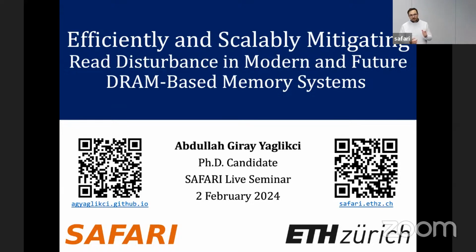That is also something critical for patchability. For example, there is a mechanism called Graphene that comes up with a very good detection mechanism based on the Misra-Gries algorithm, a frequent element detection mechanism. It implements a lot of counters inside the memory controller, and you need to define the number of counters based on the vulnerability level of your DRAM chip.